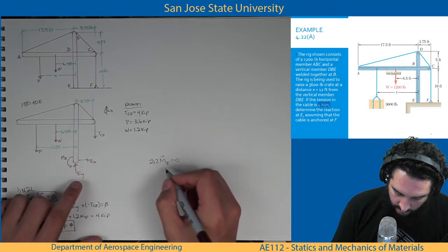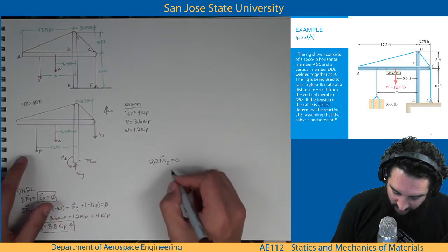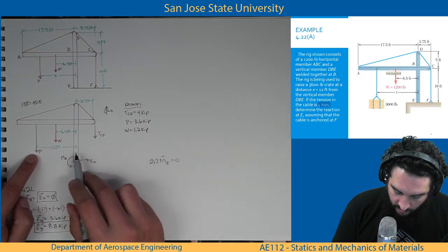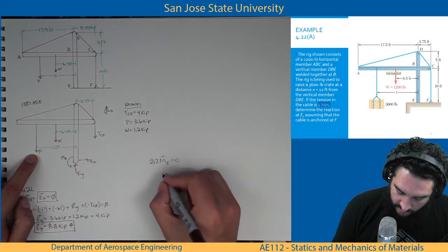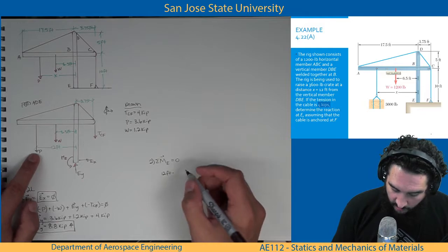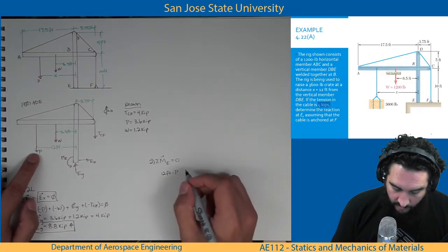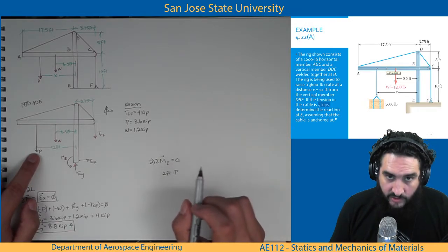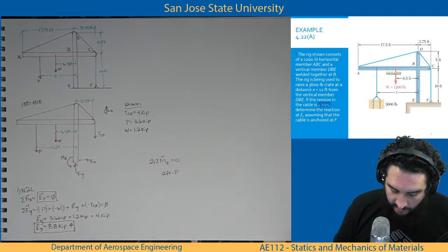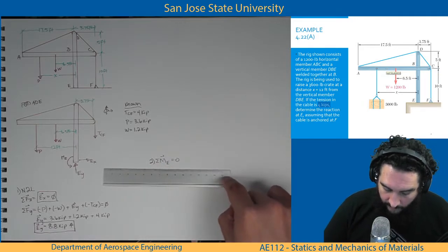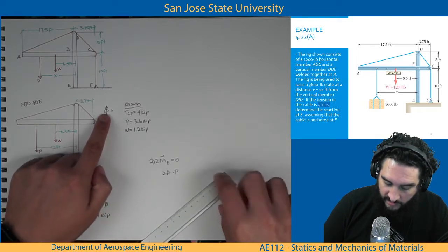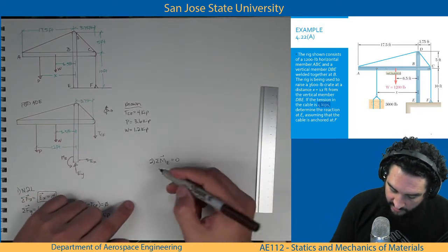So let's start with the P direction. The moment arm is 12 feet. We're going to multiply that by P. Now this is where the positive and negative comes in again. If I am at E and I apply force P, it is in agreement with the positive direction, so it will remain positive.